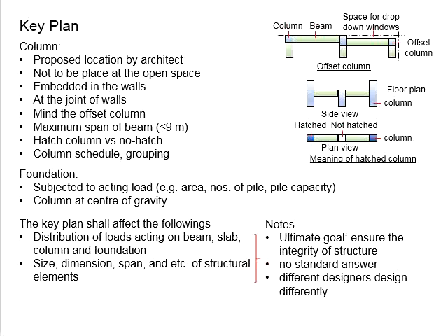Therefore, everything needs to be checked properly before the casting takes place. It is not only for the contractor. There will be site engineers also supervising the project. They will also be checking the reinforcement bar in the columns. Grouping of the columns will be helpful for them to make a quick check and increase the productivity of the works.